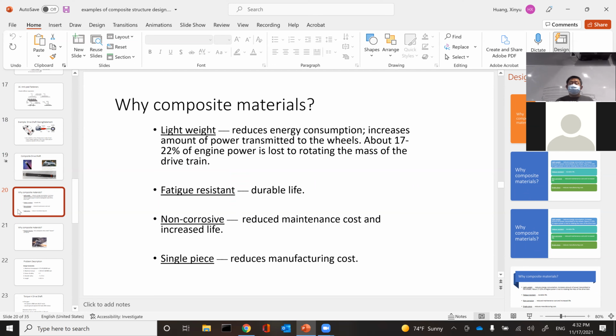If you take care of those, so you don't have graphite in contact with a less noble metal, let's say you have spacers, so you don't have an electron path between your graphite panel and aluminum or steel, then you have fewer corrosion issues. The graphite material itself has very high corrosion resistance. They don't rust. Okay. And then you can make single piece, large parts.